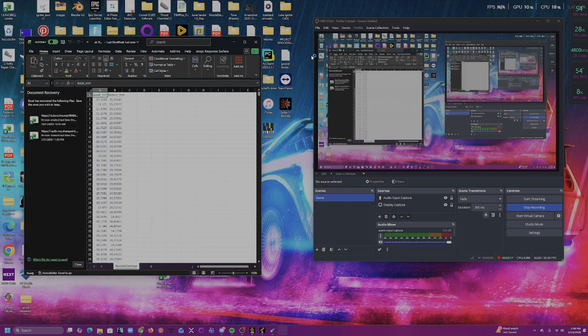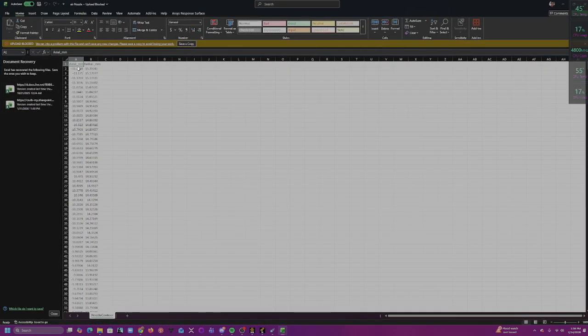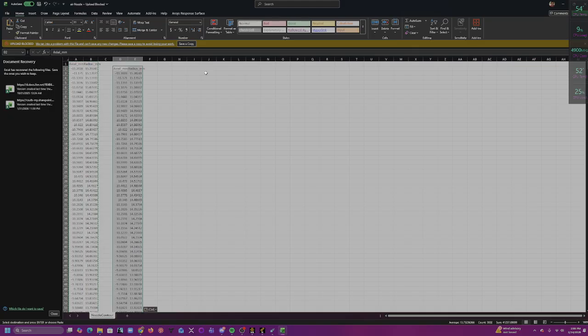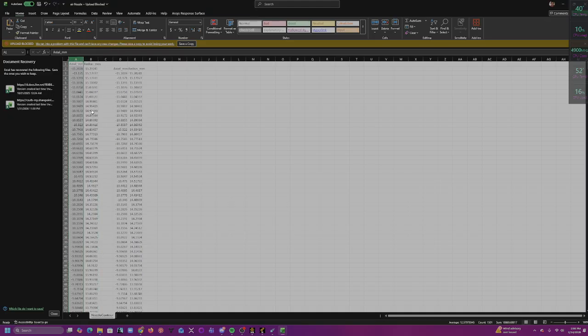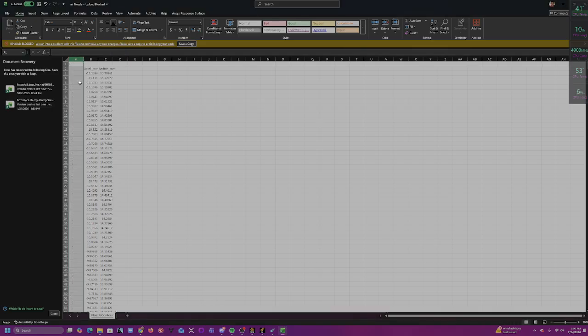Okay, so once you find it, you have all these data points. SpaceClaim doesn't like it this way. So the way we're going to be doing it is the first column is going to be a column of ones, then the second column is going to be the axial points, and then the third column is going to be the radius. So go ahead and press Control A. Let's copy this. Let's paste it right here. I'm sure there's a better way to do this, but yeah. Okay, so delete that.